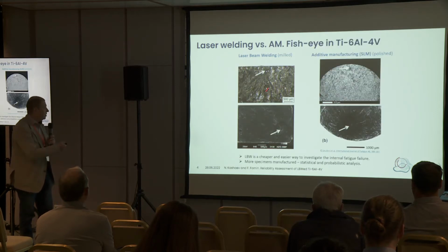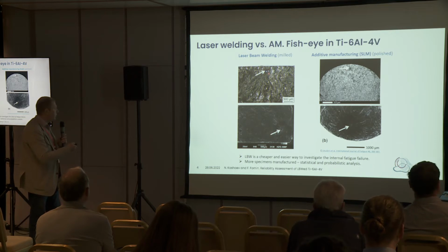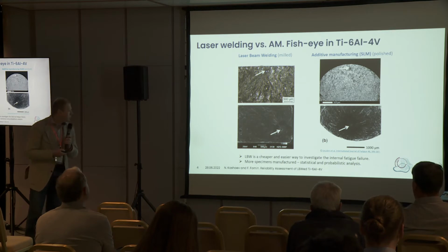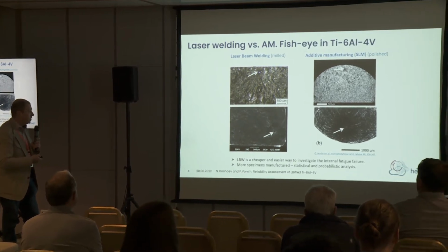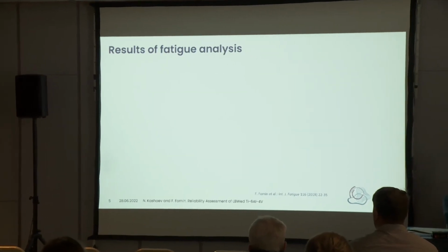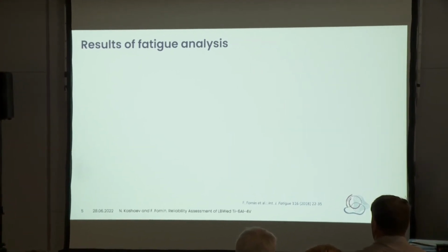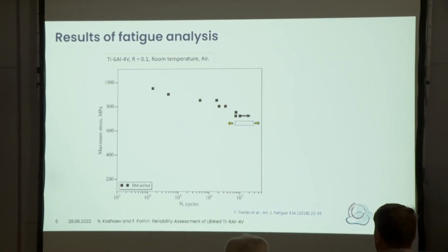If we look into the failure mechanism, we will find a lot of similarities: for laser beam welded structures, the cracks were initiated from internal porosity. The same is true for additively manufactured parts. So far, we performed our study for a laser beam welded titanium alloy, and in principle it is applicable to other manufacturing processes.